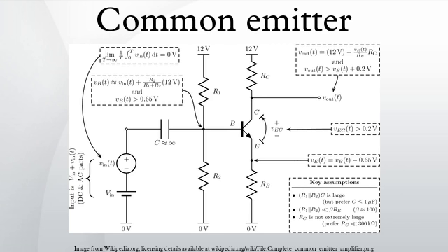The problem can be mitigated in several ways, including reduction of the voltage gain magnitude, reduction of the output impedance of the signal source connected to the base, using a cascode configuration, which inserts a low input impedance current buffer between the transistor's collector and the load.